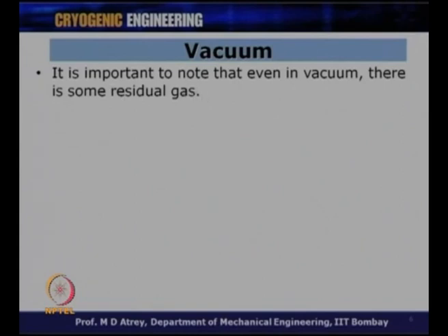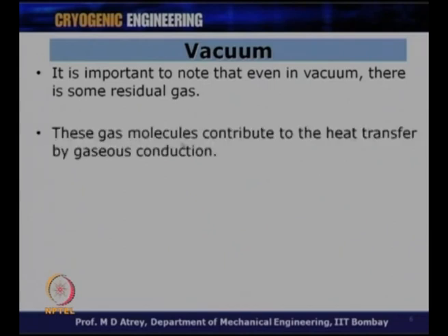It is important to note that even in vacuum there is some residual gas. Now, this is an additional aspect I had not talked about. Depending on the level of vacuum, there will be some gas, and this gas also would cause some gas conduction. These gas molecules contribute to the heat transfer by gaseous conduction. In comparison, this gaseous conduction is going to be very, very small. However, depending on the degree of vacuum, these gas molecules will contribute towards heat transfer by the mechanism called gaseous conduction, which will depend on the conductivity of the gas.